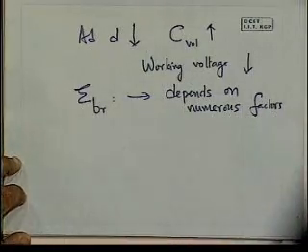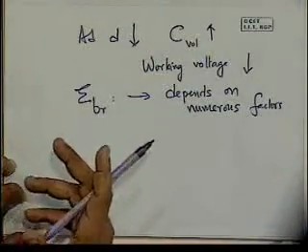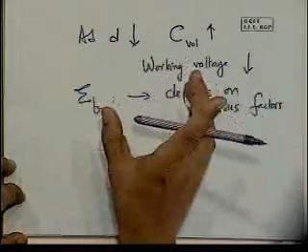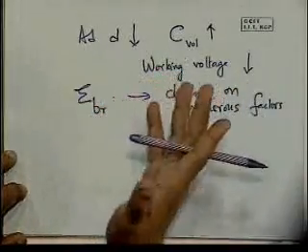So I can't just look at some value of the breakdown strength to determine what should be the operational voltage. Under different circumstances, the breakdown field strength, something as simple as there's dust on it, theoretically it should be able to sustain a greater field, but because of dust it got shorted out and broke down.